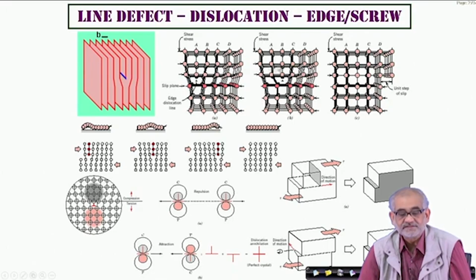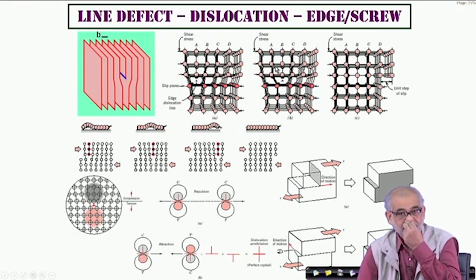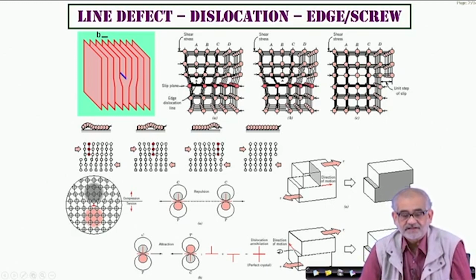So that means there is a closure failure, and the closure failure, dimension-wise and direction-wise, defines a particular characteristic feature called the Burgers vector, which defines exactly the existence and the dimension of a so-called edge dislocation. Whenever you have such an extra half plane introduced inside the crystal, this blue line here defines the end of this extra half plane.